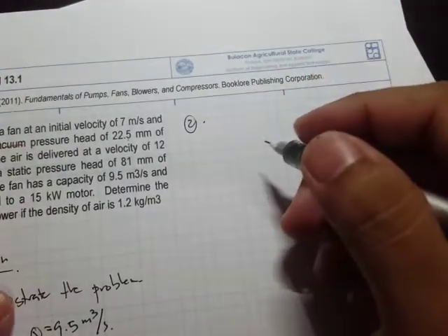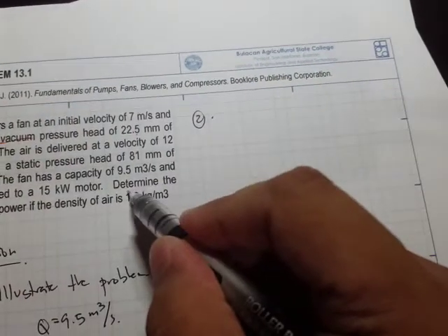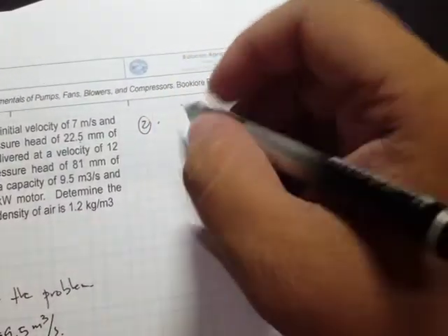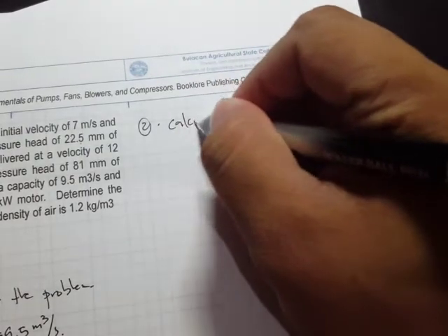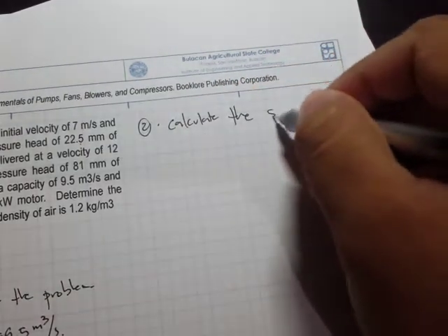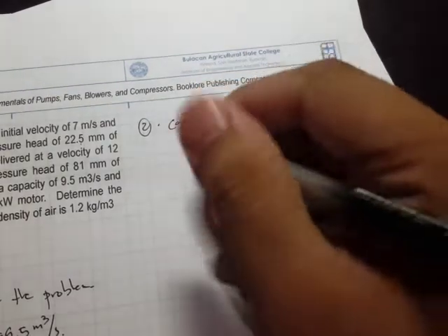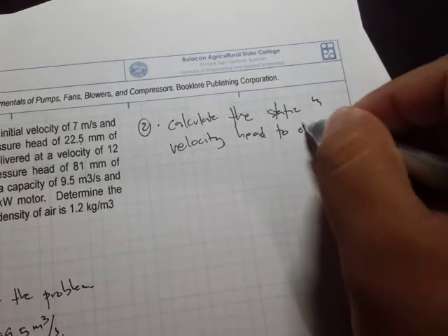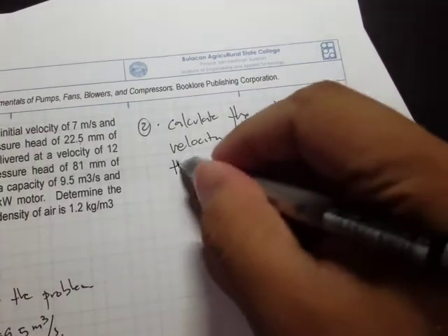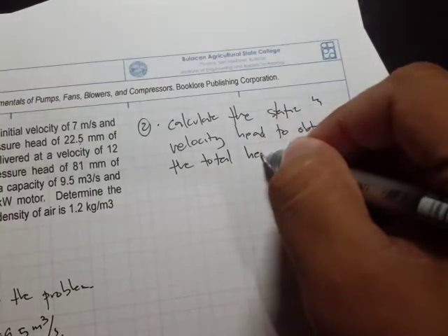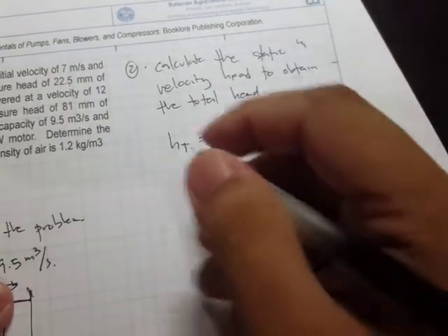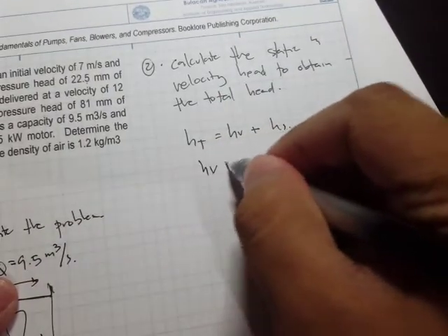Right, so that's it. So now let's solve. We are only asked to solve for the total air power. So if we solve for that, we need to calculate the static and velocity head to obtain the total head. Right, so H_t is equal to H_v plus H_s, and H_v, we know that